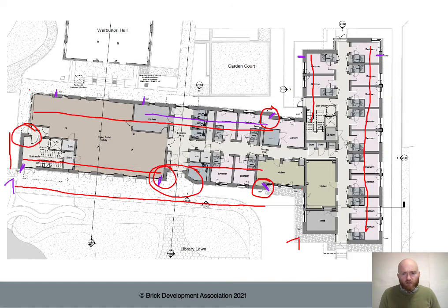There's nothing down towards this bottom section, so maybe we need to introduce a movement joint in the middle of this panel here, if the brickwork is continuous above the windows, or maybe you could introduce something within the window if we have a natural break there. Again, it gets a bit more complex if we have lintels spanning that movement joint, and it's probably outside of the scope of what we can cover in this introduction.